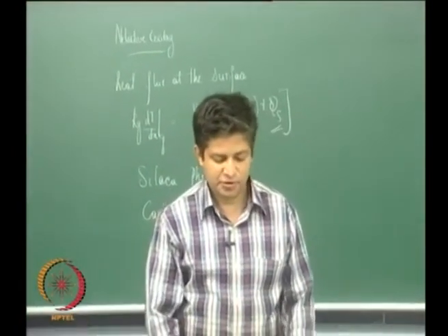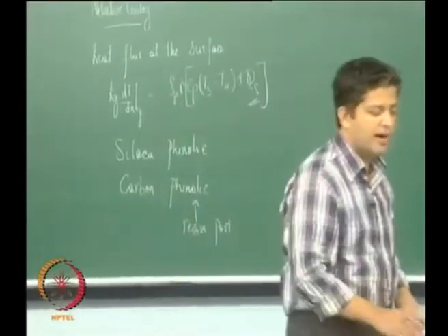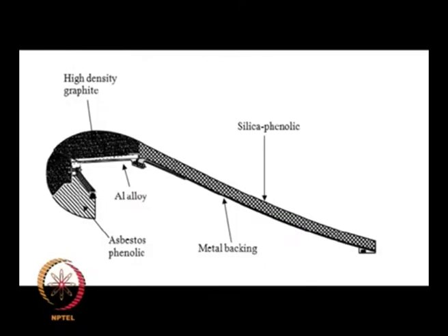Okay. So a combination of, if you look back at this picture here, this is the convergent portion, this is the throat, and this is the divergent portion. This is the axis, so we have shown only one side of the axis. Now if you see here, the highest heat transfer is near the throat, which is protected by 2 layers.